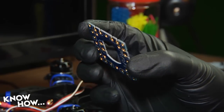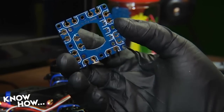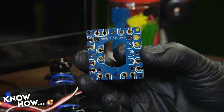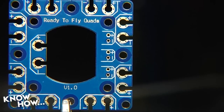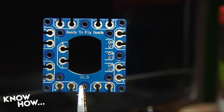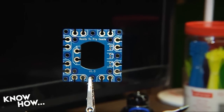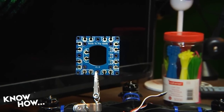The next step is to make a power distribution harness to connect the ESCs to the KH250's power source, starting with a 45mm power distribution board. The traces on the board will distribute power from the positive and negative leads on the inside of the board to devices that are connected to the positive and negative leads on the outside of the board. The board comes with soldering points for 8 ESCs and 3 peripherals, but we're only going to use the 4 sets of points towards the left and right of the board.